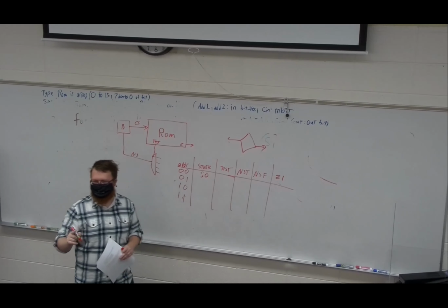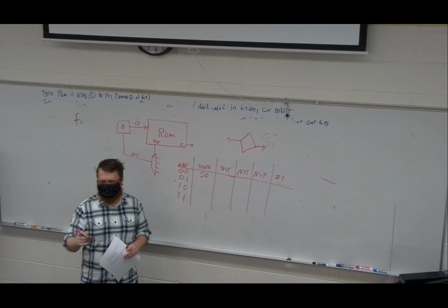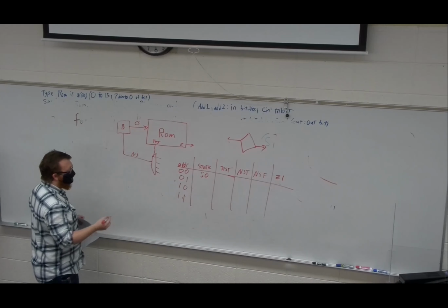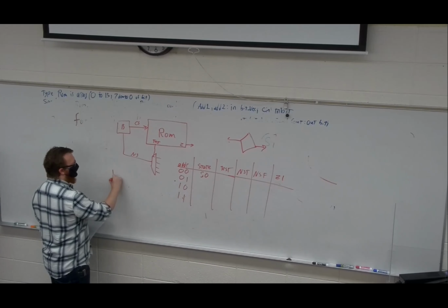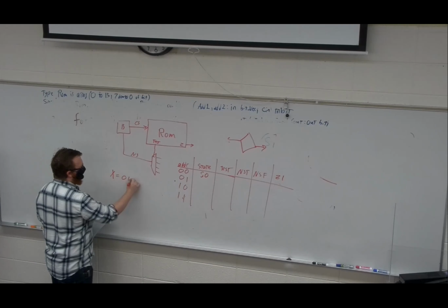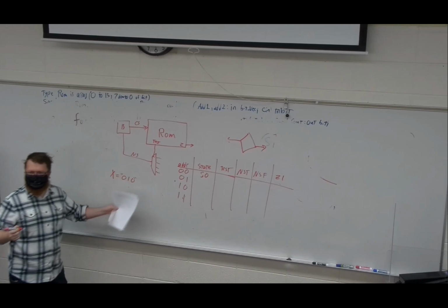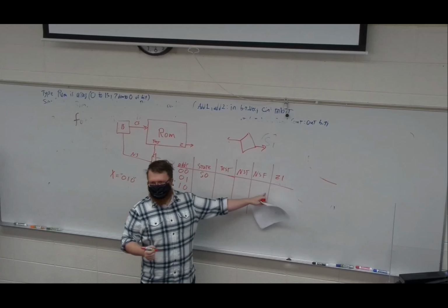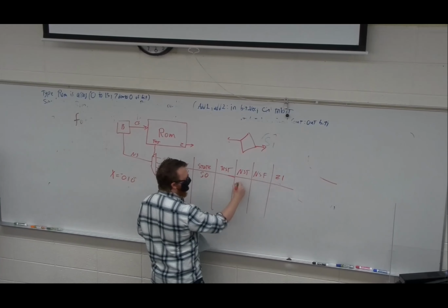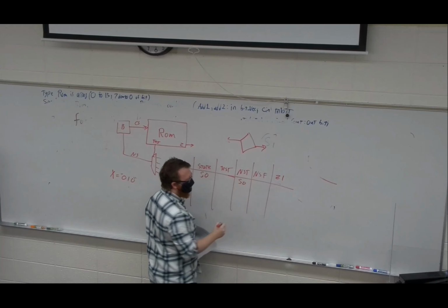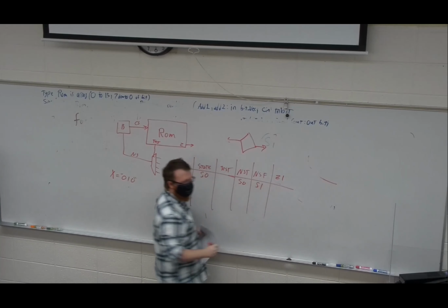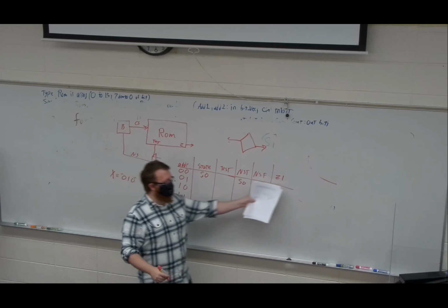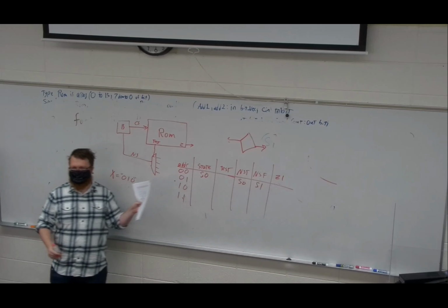One of the main things that you're looking for is it can only do one test in microcode, right? And a microcode test can be more than one bit. You could ask something like, is X equal to 0, 1, 0? Right, that is a valid test. But the decision is either true or false. So it might be next state true, stay in state 0, next state false, go to state 1. Right? And then what are the outputs doing when I'm in each of these states?